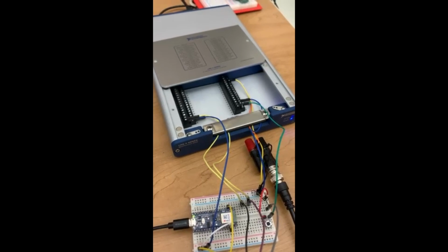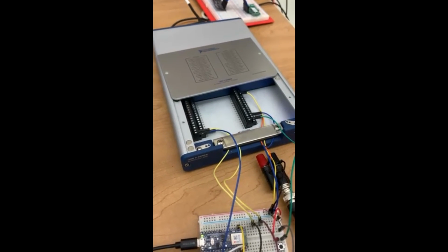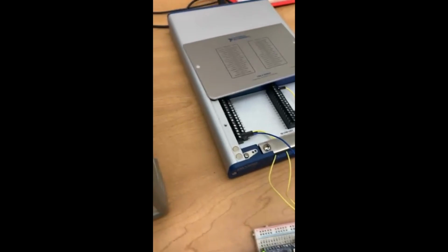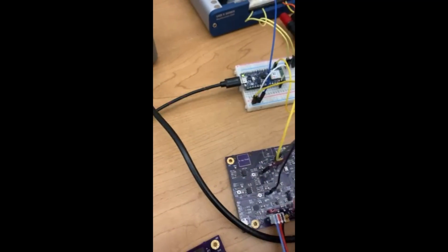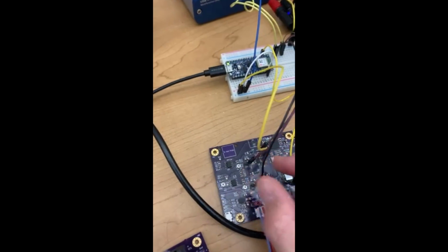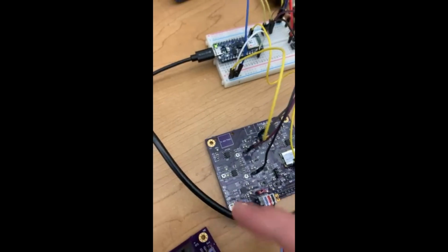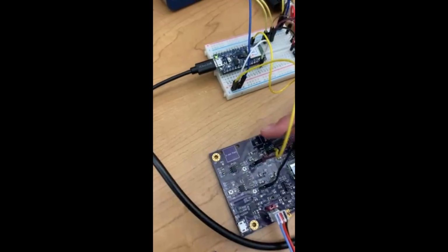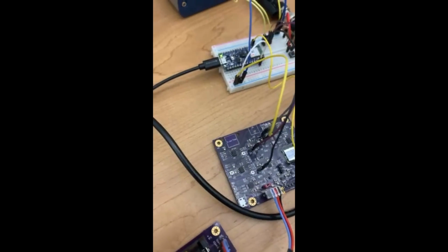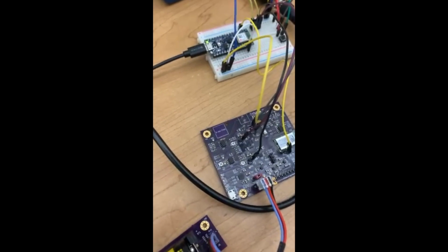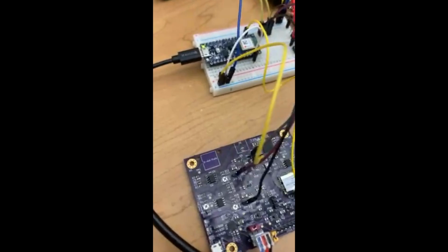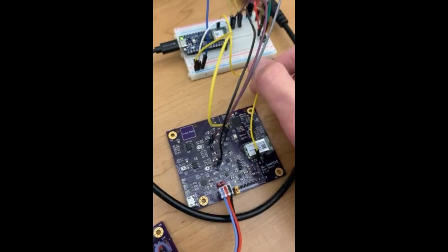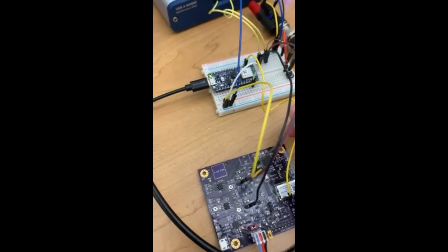In order to simulate this, we're using a USB 6351, which has two analog outputs that are able to output at the same sample rate as our simulation data. Those are fed from our analog outputs through to the ADCs of our PMU, one for voltage and one for current. The PMU normally has a D-dot plate for sensing voltage and a Hall effect sensor for sensing current, which would be useful for a real grid, but we can't generate signals large enough for our PMU to sense. So the PMU will sense this phasor data and then transmit it to the Arduino using a serial port.